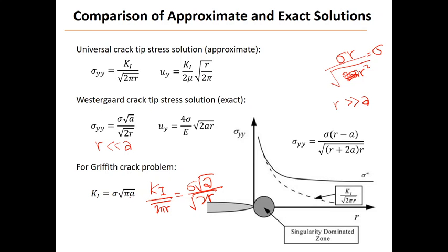If you recall, the square root of crack length appears in the Griffith solution when we deal with the energy release rate. It appears in Inglis's solution when he tried to find the stress around the crack tip, around an elliptical flaw. So the larger the a, the larger the crack, then you increase K1, which means you intensify the applied stress even more, right?